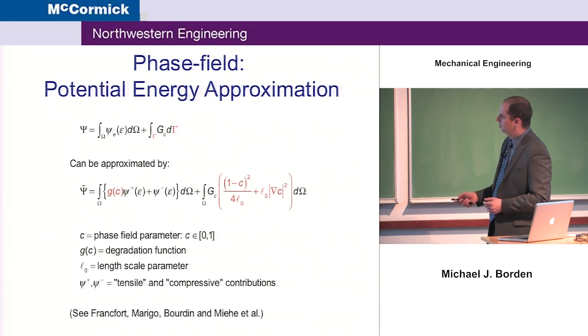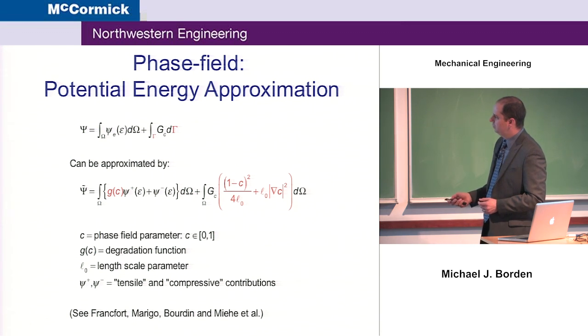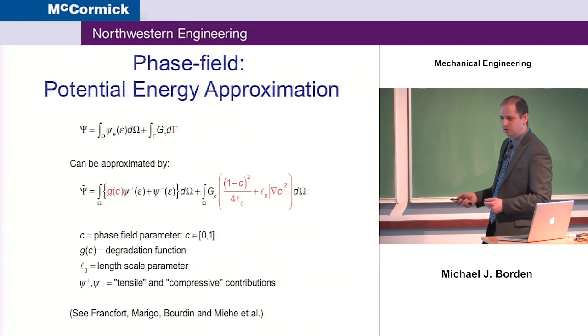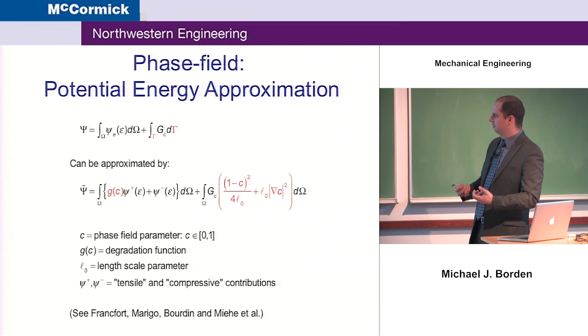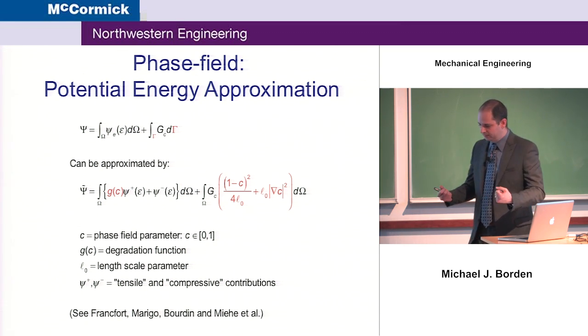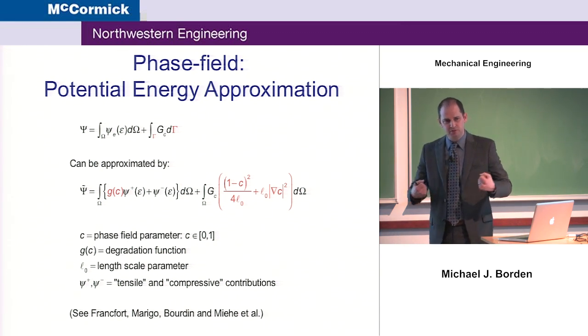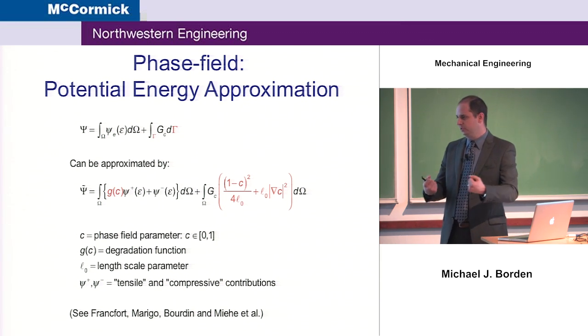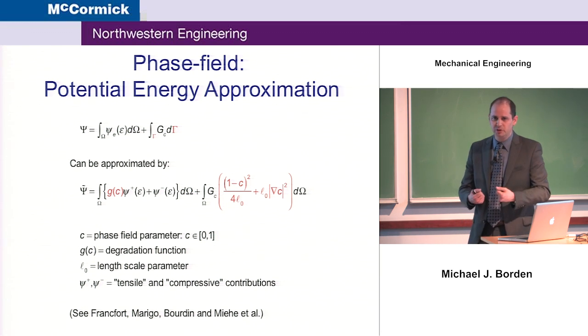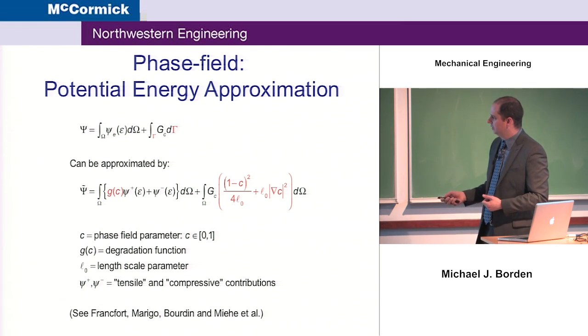And then for the strain energy, we do a decomposition where we have a compressive component of the strain energy, and a tensile component. And then we have this function we call a degradation function, which is only going to reduce the strength of the tensile component of the strain energy. And we find this important in a lot of cases that if you're reducing the compressive strength, especially in dynamics where you have stress waves, that you'll get spurious cracks where you get some kind of a compressive stress peak. And so it's important to have this decomposition.